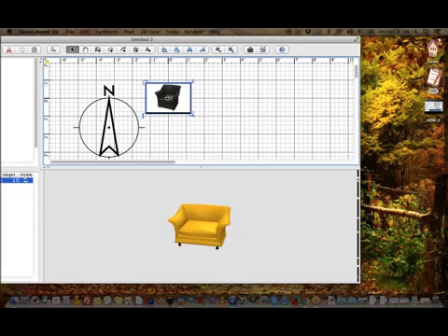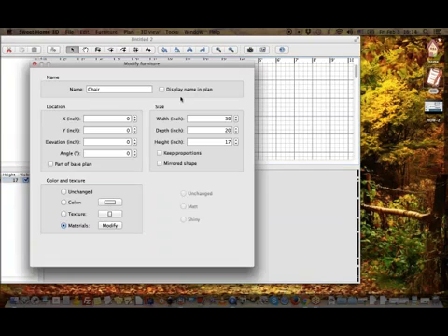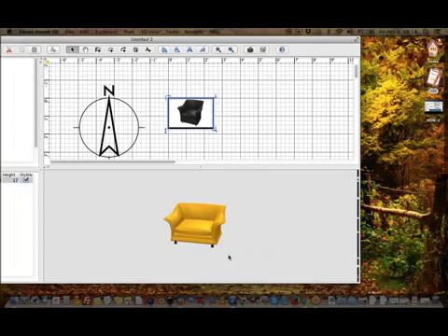So this is actually situated on the 0, 0 point, but that 0, 0 is in the middle, and I want it to be on this corner. So what I'm going to do is basically divide the width by 2. I'm going to set it to 15, divide the depth by 2, set it to 20, okay?